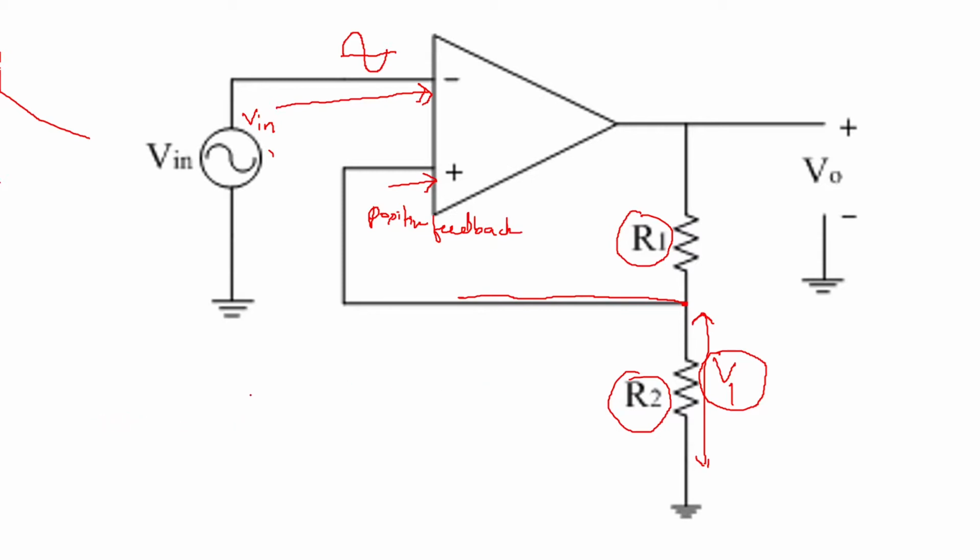Now, if you see the superimposing of the two inputs, where one input is a sine wave like this, this is a regenerative comparator circuit. One threshold voltage will come here, which will be called the upper threshold voltage, and one voltage will come here, which will be called the lower threshold voltage.